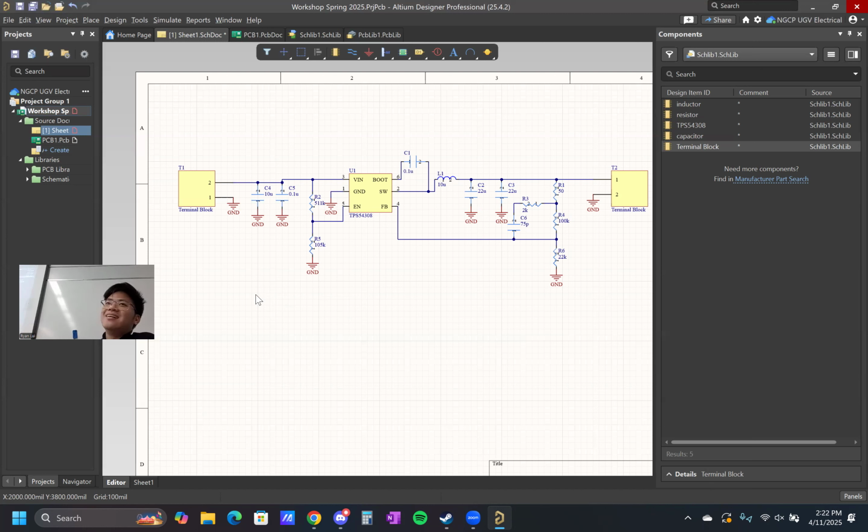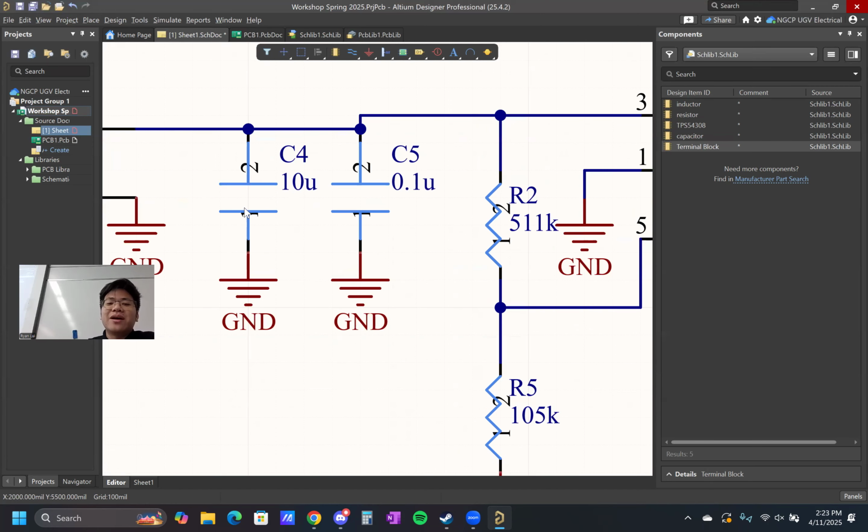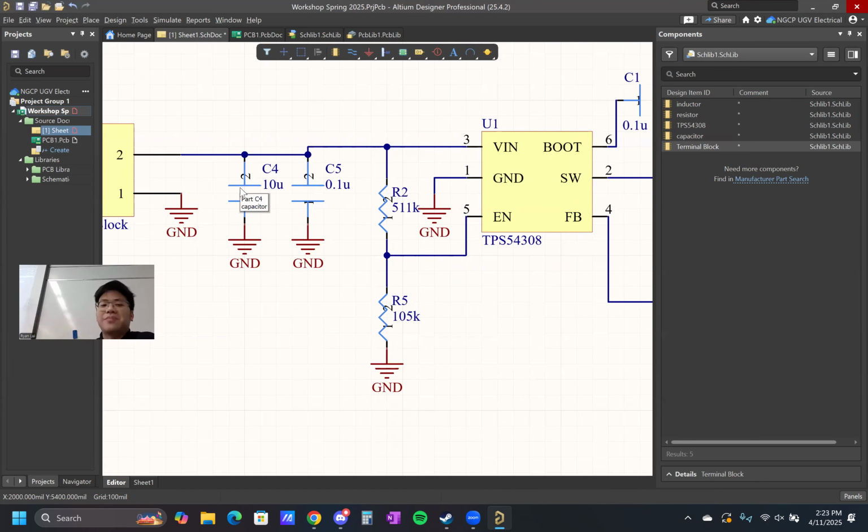That's all you need. The rest is for documentation, for working together with other people. But it's not going to throw you an error just because it's off the sheet. This is a schematic. It's decorative. The capacitor symbol doesn't matter. You could have made this a smiley face. It doesn't matter. The pins are what matter. The labels are what matter.